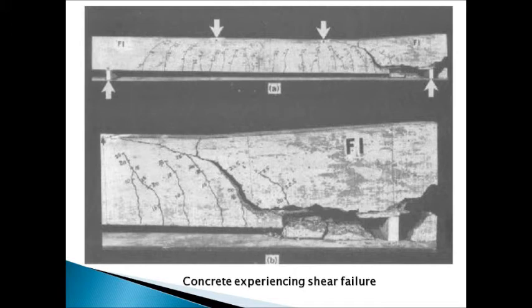Concrete is strong in compression but weak in tension, and there is a tendency for concrete to crack on the plane subject to tension. When the tensile stresses are so high, it is necessary to provide reinforcement. The design of shear reinforcement is to provide steel to cross the diagonal tension cracks in the concrete and subsequently keep them from opening. Shear reinforcement increases the ultimate shear capacity of a bending member. Hussein shall now tell you what shear reinforcement is.